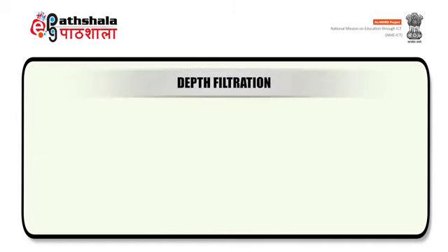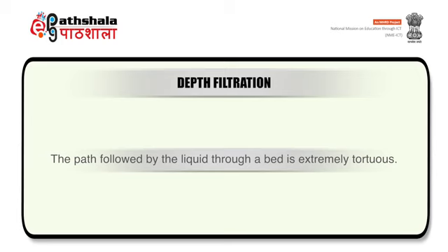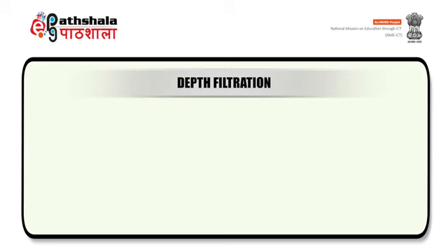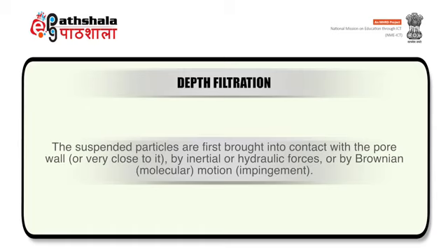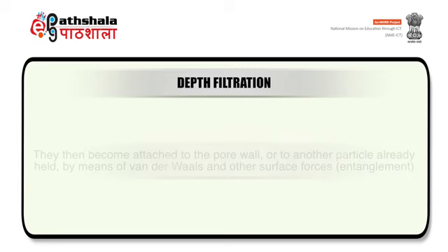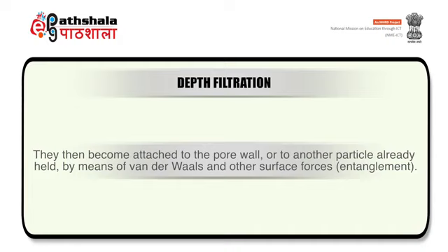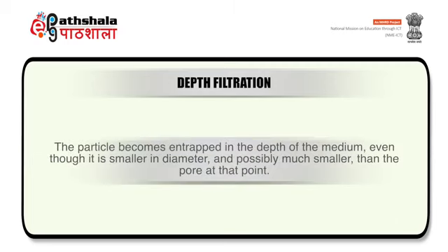The third is depth filtration. The path followed by the liquid through a bed is extremely tortuous. The suspended particles are first brought into contact with the pore wall by inertial or hydraulic forces or by Brownian motion. They then become attached to the pore wall or to another particle already held by means of van der Waals and other forces, that is entanglement. The particle becomes entrapped in the depth of the medium even though it is smaller in diameter and possibly much smaller than the pore at that point.